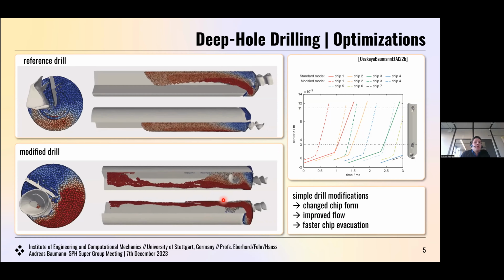Thereby we can apply a model order reduction technique, a modal reduction, which gets rid of all the high frequency oscillations of our flexible model. We only concentrate on the low frequency deformations, which are actually of interest to us.